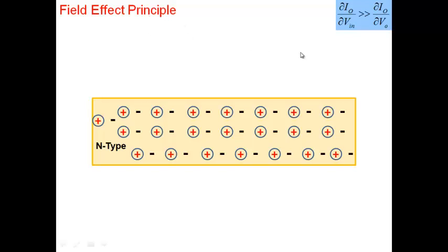Okay, and so with that in mind, let's take an N-type semiconductor. An N-type semiconductor, all of you know, will have donor atoms, which are ionized at room temperature, at least. And these donor atoms give rise to electrons. So I have all these donor atoms inside my semiconductor, along with all these negative charges. The electrons are there. So we have all these donor atoms and electrons, and donor atoms, of course, are immobile. They're fixed in their positions. Electrons, of course, can respond to voltage and can move.